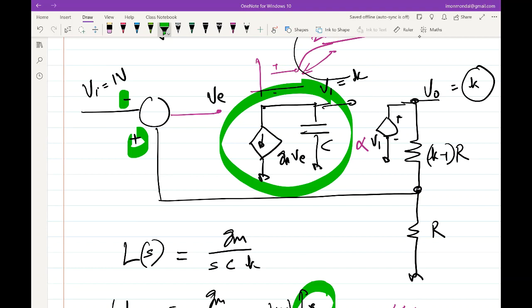feedback. So his question is, even in the ideal op-amp that we are so used to, we always seem to connect the output to the negative terminal. But that need not necessarily be the case, because what if there is another inversion in the loop? It might be another transistor, maybe something else. So whatever you mark as positive for the op-amp might end up being the negative terminal for the overall feedback. Essentially, what you have to be aware of is the sense of the overall loop.